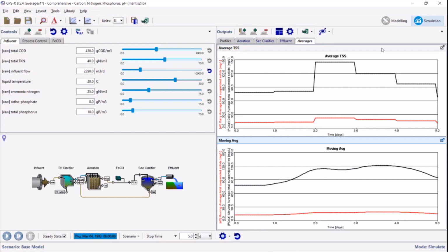And here you can see the difference between how the daily average looks and how the moving average looks, right? This is carrying the information along over a longer period of time, right? This is already starting to come down, but this is still looking 3 days into the past. Whereas this is only using 1 day of information as it goes by. So it's a way to kind of hang on to information, to have a little bit of a history of where the state of the process is, and use that in your control algorithms potentially.